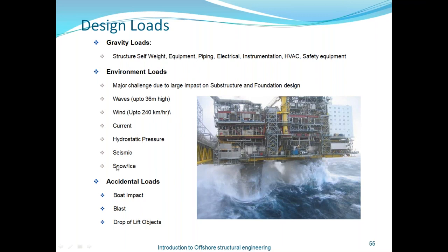The critical load for offshore structures is environmental load, in other words, wave load. So wave load is critical for offshore structures. The major challenge is to create a proper jacket, I mean substructure. In the next session, when I say substructure, it means the jacket, and foundation means we call piles.